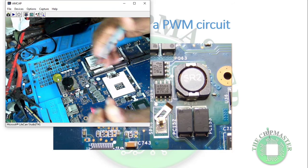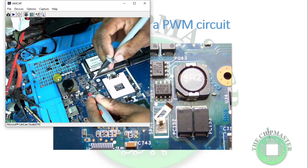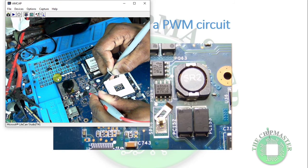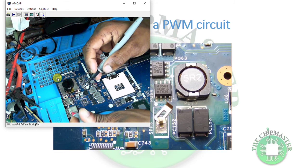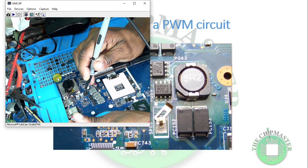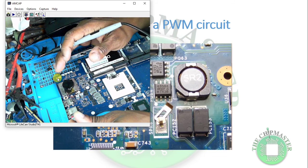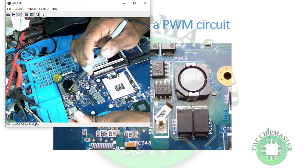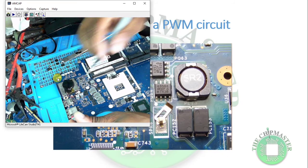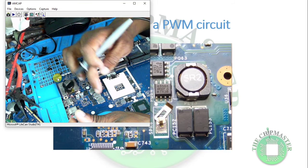Alright, so this is the upper MOSFET, and it is connected to the coil. Let me see this MOSFET. Sometimes they use 2 lower MOSFETs, yes, because the CPU power supply is so large. The CPU power supply needs 2 MOSFETs to switch in, because if you normally use 1 upper and 1 lower MOSFET, the CPU power supply current is shared, right?